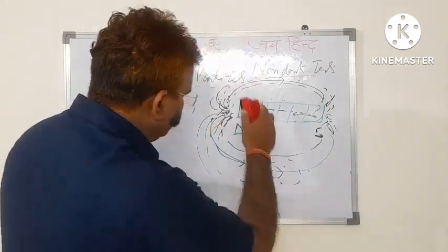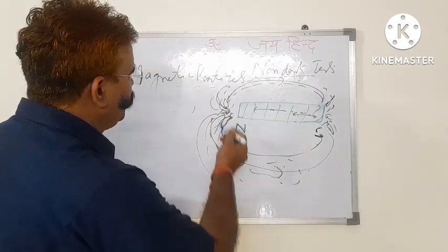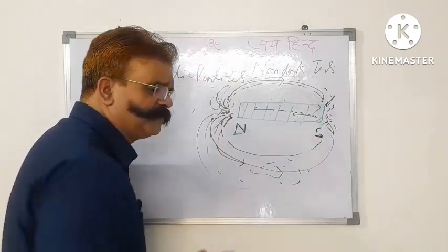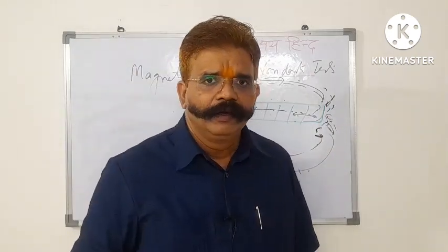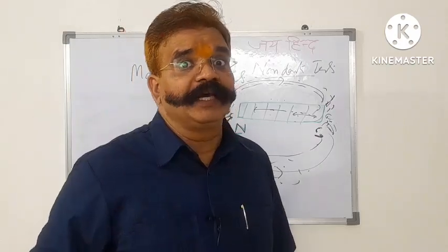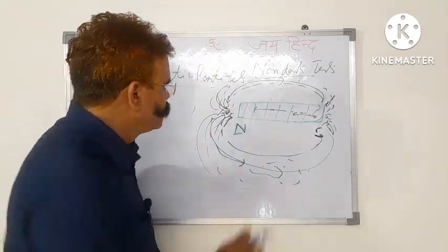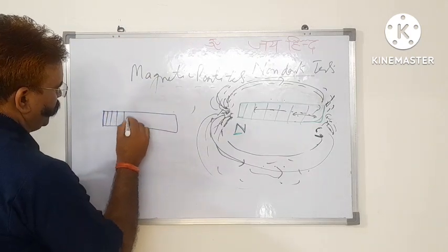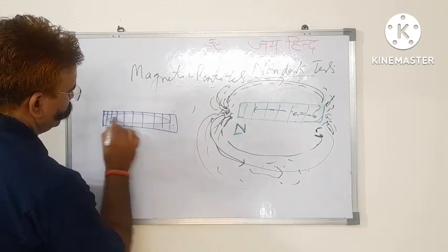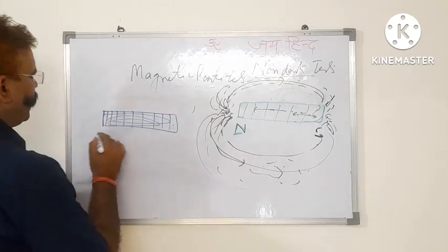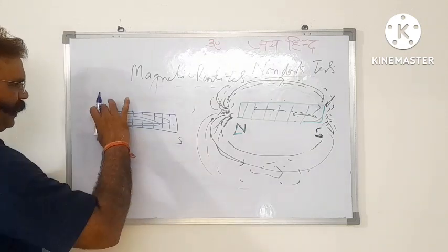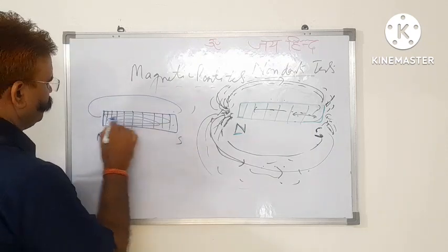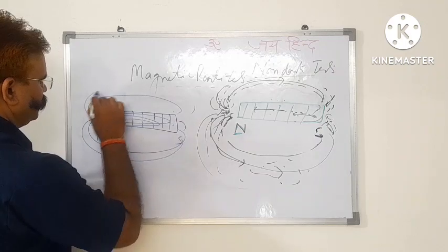In this topic, we derived that the magnetic flux density is highest at the pole pieces where the north-south poles are. So what happens in the case of crack detection? Suppose there is a rod, a component of some sort of engine. We have magnetized it, then due to this magnetic field, north-south poles will be formed and the magnetic lines of force will start traveling like this, like this, like this.